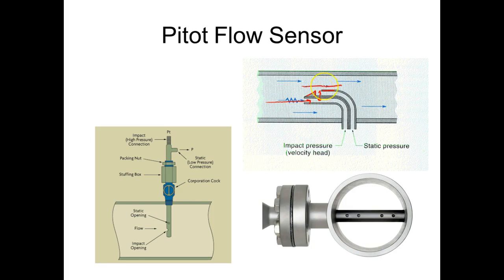So this is exactly the way they measure airspeed on an airplane. As you go up, the air gets thinner, and the static pressure goes down. They compare that to the ram pressure, and it gives you the airspeed, wherever you're going. Of course, we had different methods. Most airplanes, except for the 737 MAX, have multiple backups for what they measure. So the MAX only had one angle of attack sensor, and they didn't have any way of knowing it was bad.